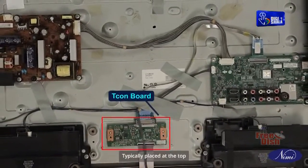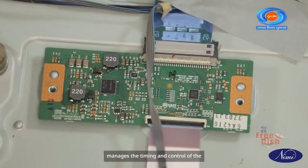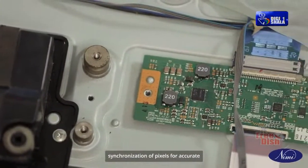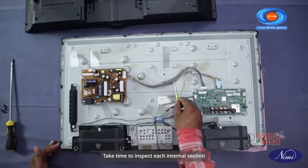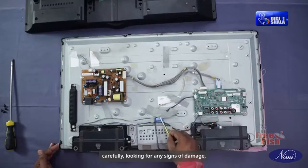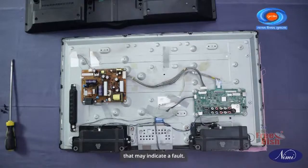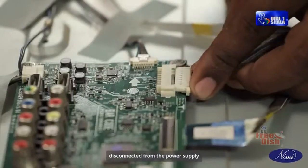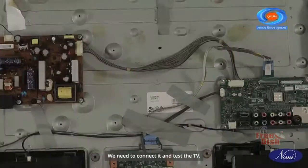Typically placed at the top center or back of the TV, this board manages the timing and control of the display panel, ensuring proper synchronization of pixels for accurate image reproduction. Take time to inspect each internal section carefully, looking for any signs of damage, loose connections, or burnt components that may indicate a fault. As you can see here, there is a cable disconnected from the power supply to the main board. We need to connect it and test the TV.